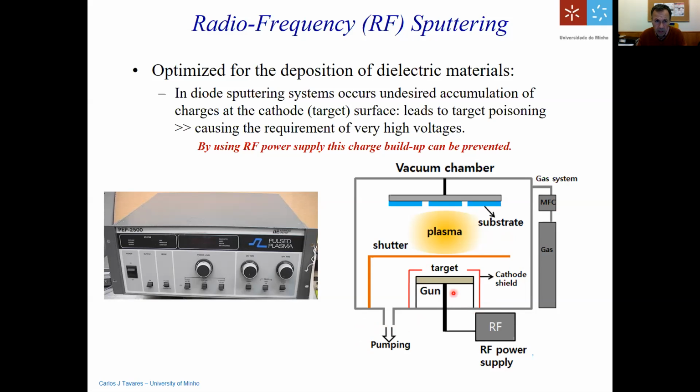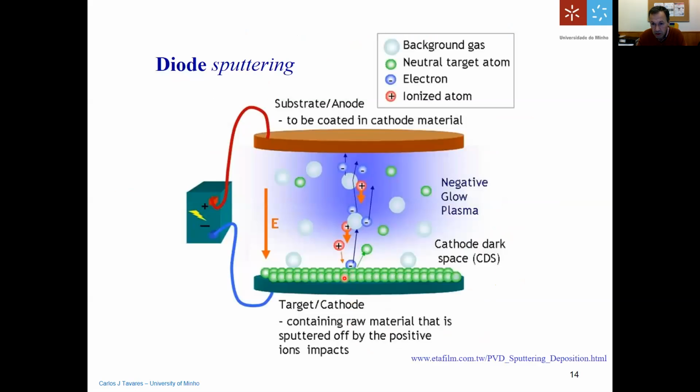Okay, and additionally, the radio frequency power supply is actually more important when your target is not conductive. For example, if you're using titanium, it's conductive, it's okay, but you can still use radio frequency, it's no problem. But if you're using, for example, a polyamide target, you can also use a polymer target to sputter polymer chains. Okay, if you're using, for example, a polymer or silicon, which is also not very conductive.